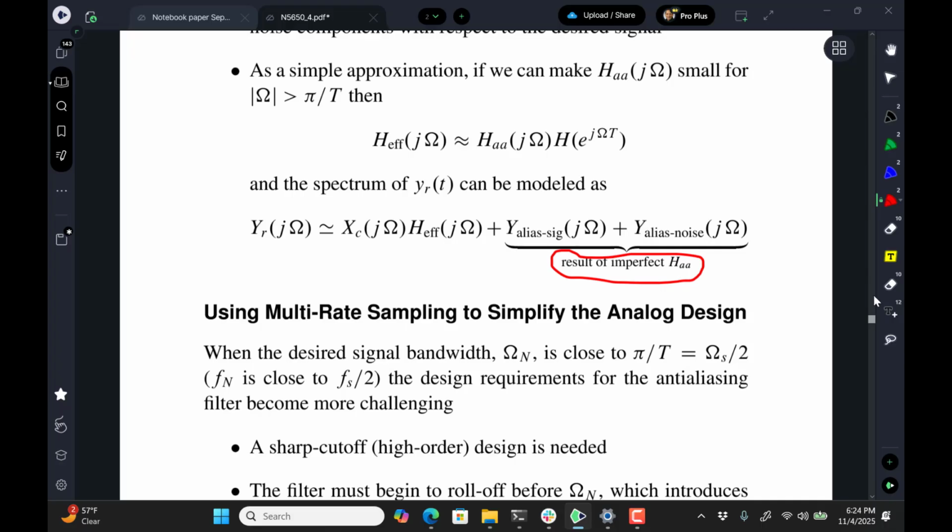We'd like it to be small, but it can only be so many dB down, and you're familiar with that from analog electronics, right? You have so many dB down outside the passband, and maybe you want that to be 40 dB down. What do you think in digital filters? We generally are looking for 60 dB down or more, just depending upon the application.